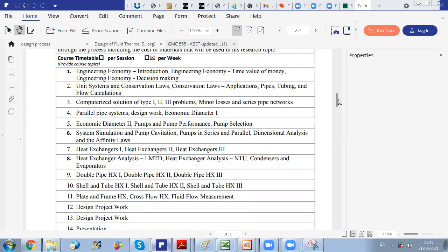We will transform these differential equations into algebraic equations by using, for example, the finite volume technique, or finite elements, in order to solve for this. You will write your numerical equation, one for temperature, one for velocity, one for concentration. Of course, it will be very hard to do it on your own. This is why there are a lot of software packages based on computational fluid dynamics.